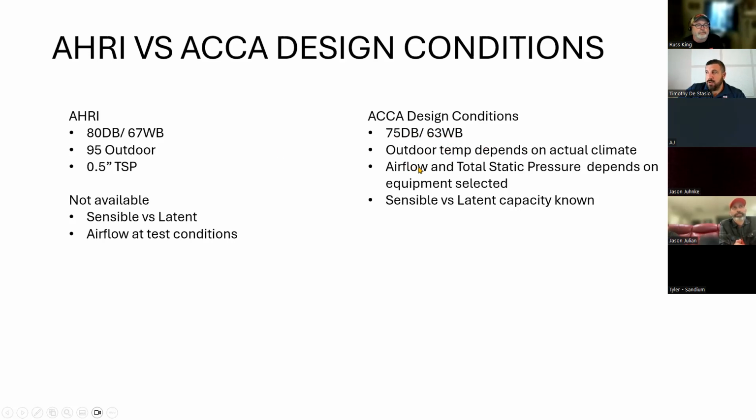You're going to select a unit. The airflow and the total static pressure depends on the equipment that you select. You've got to make sure your unit can move that airflow at the static pressure. And you're going to need to know what your sensible and latent capacity are.